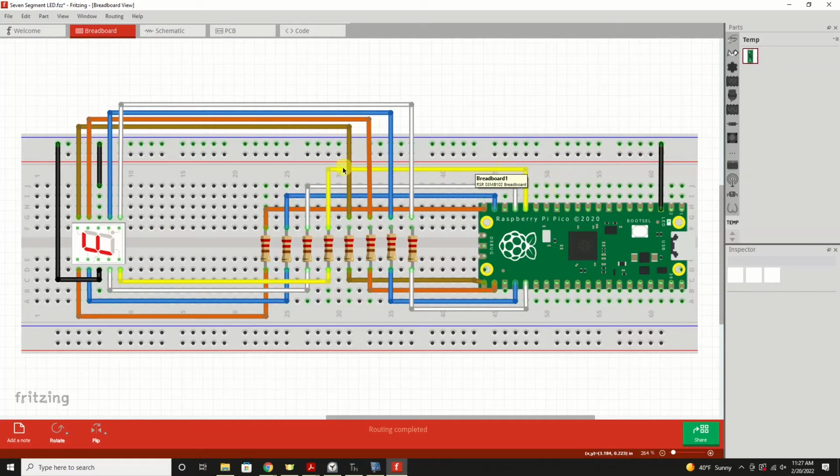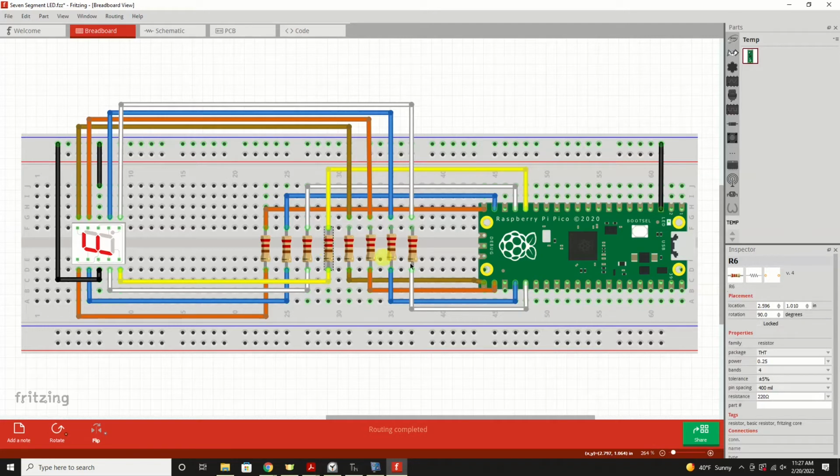And what we have to do is go through our current limiting resistor. And I've picked 220 ohm for the resistor just because when tinkering on a breadboard, I'm not necessarily looking for maximum brightness or anything, but I am looking for protection so that I don't short something out. And if I do, having a higher ohm resistor, we can protect the circuit or the device from being burned out. If you watch my bar graph video, I burned out one of them by short-circuiting something, one of the little segments. But you would use the actual value in your actual circuit.